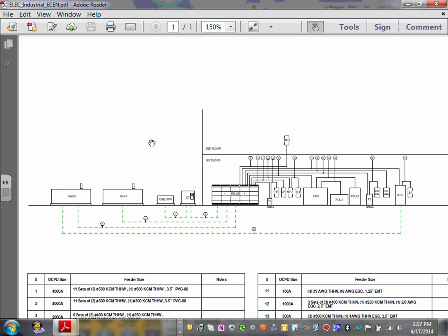Then you get into another chunk of load, which is the mechanical panel. Every building you walk into has lights and receptacles, and then you have to have some type of heating, cooling, ventilation system. So if your building is big, you think, okay, I'm going to allocate another chunk of load for my mechanical equipment: mechanical, heating, cooling, ventilation, rooftop. These could be one panel or multiple panels based on the size of the system. So I have a mechanical panel.